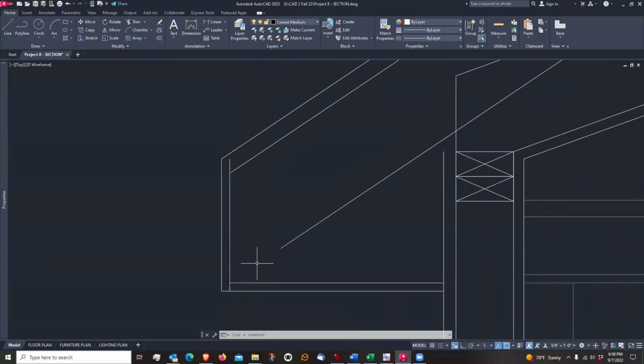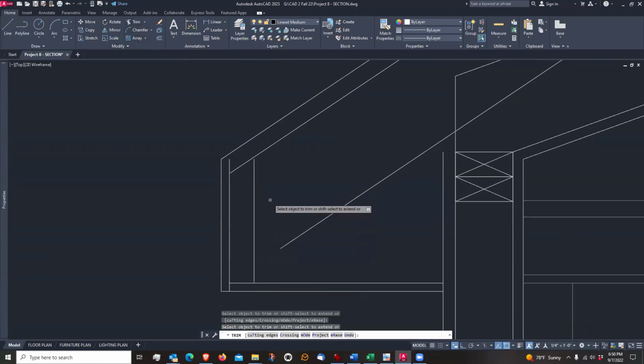All right. And then there is going to be another joist over here. So I'm going to offset 1.5 inches. And this is just going to be a 2x8 over here, but I'm just going to draw it simply. So I'm using my trim tool to trim here, and then I'm going to hold shift and extend up here.